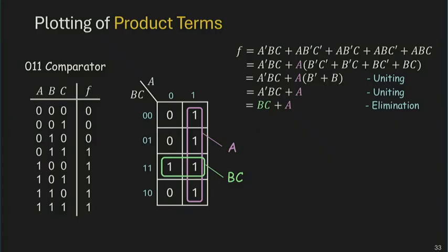The way it works in a Karnaugh map is, again, by grouping together neighboring ones. You have this whole column of ones, and that can be viewed as a single group, which can then be represented as a single term. That group essentially corresponds to the condition of A equals 1. A equals 1 corresponds to that half of the Karnaugh map. So these 4 ones can be together, represented using a single term of just variable A.